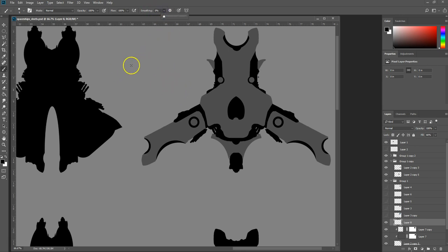Basically the way the smoothing works is it's like a lazy mouse, if you've ever used anything like that. So if I draw without the smoothing, I can just do really rough. I mean, I'm drawing with a mouse at the minute, which is why this stuff's a bit rough. But if I turn the smoothing on, to like 66, and I've got the pull string mode on here at the minute, if I switch that off, what you can see is it basically follows where I'm pressing it.